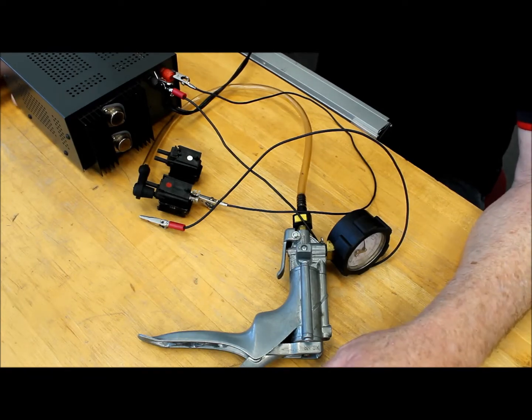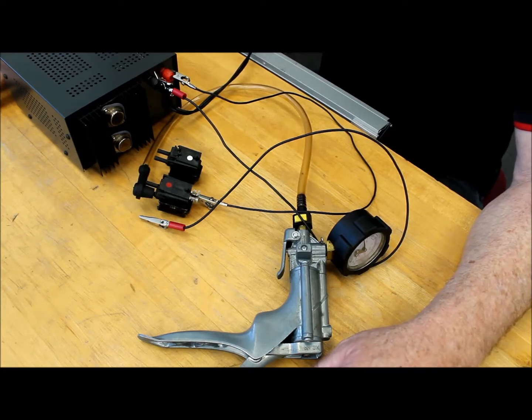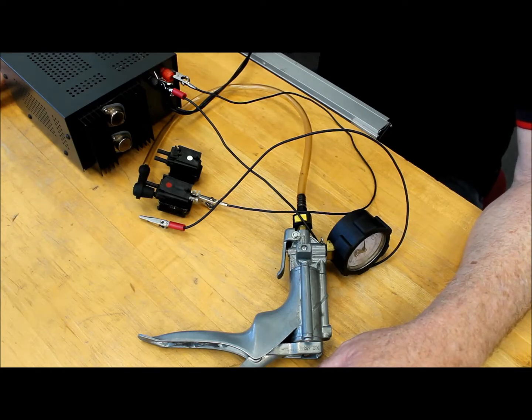So these sorts of solenoids are used to control vacuum to various devices, EGR valves in the old days. It could be controlling vacuum to something in the AC and heat system, to move a door if it's not an electronic system, all kinds of different applications for vacuum control solenoids. And they come in both varieties, like I said, normally open, which means they're open until you energize it, and normally closed, which means closed until you energize it.